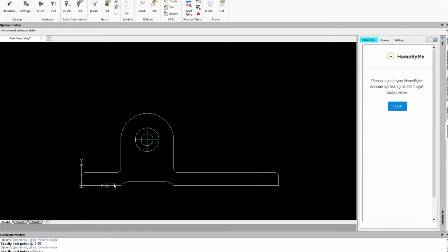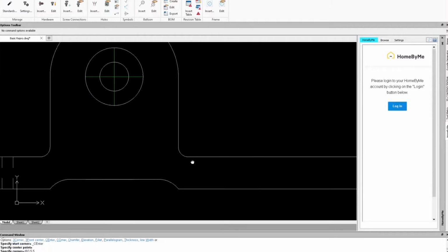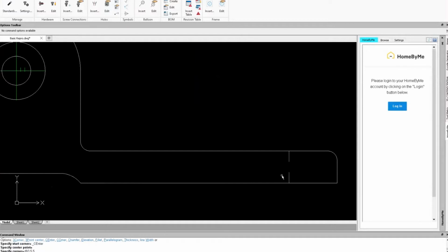Well, to add these hidden lines, all I need is rectangles. So if I turn on my rectangle tool, go to the right direction here, rectangle, and I turn on an option called CE for center rectangle, I get an option to go 3.5 by 5, and it automatically creates that center line, that hidden line for that rectangle.